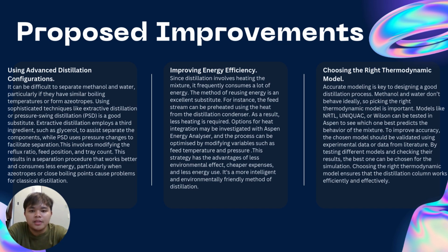Next is improving energy efficiency. Since distillation involves heating the mixture, it frequently consumes a lot of energy. The method of reusing energy is an excellent substitute. For instance, the feed stream can be preheated using the heat from the distillation condenser. As a result, less heating is required.